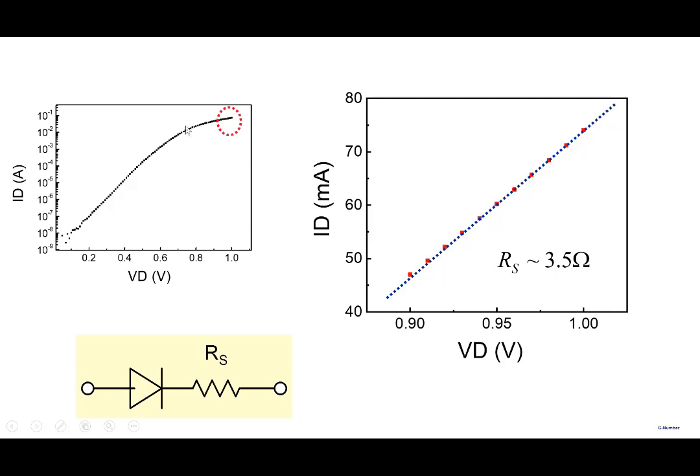It's for that reason that we normally don't operate the diode at 0.9 or 0.95 or 1 volt. It's no longer exponential, it's linear. And linear means that if you double the current, the diode voltage would also double. You don't want that from a diode. In the normal applications that we use, we want the diode voltage in forward bias to be as small as possible.